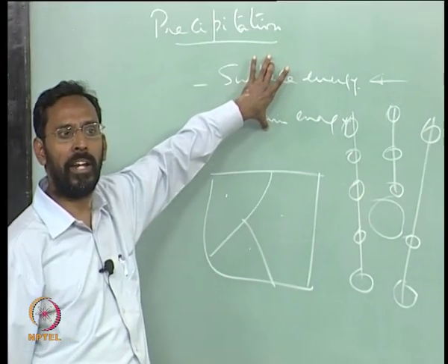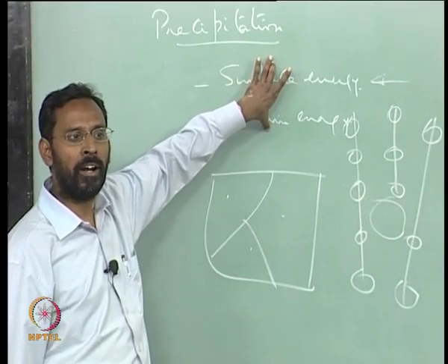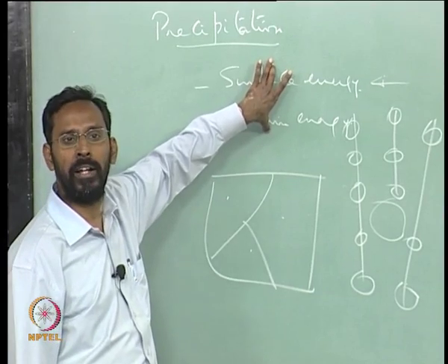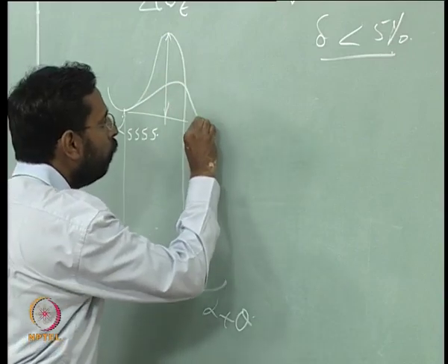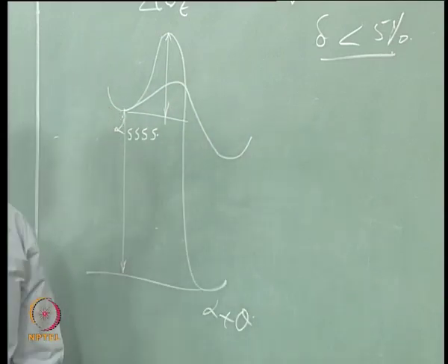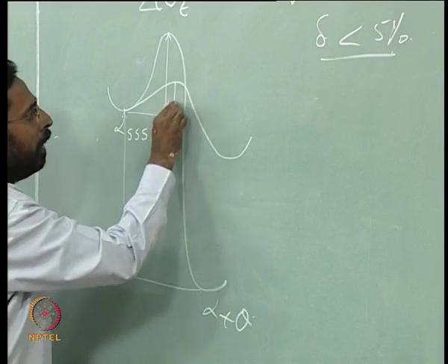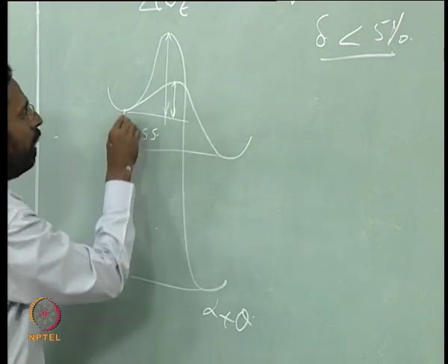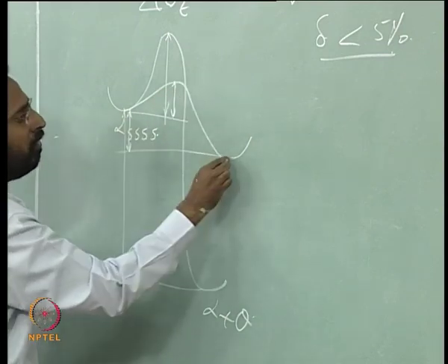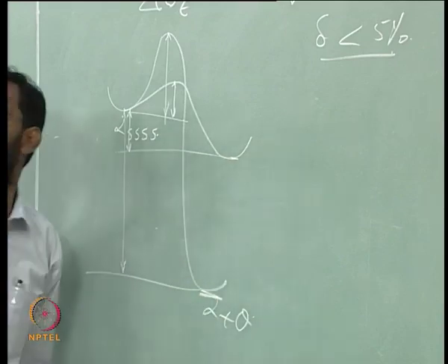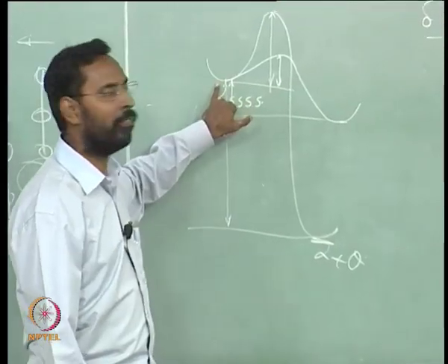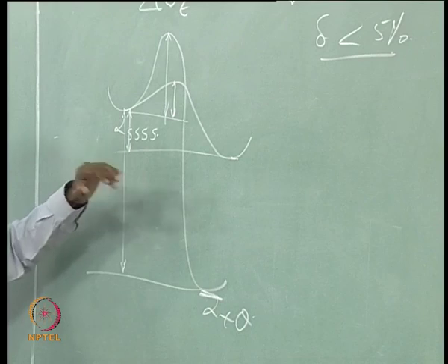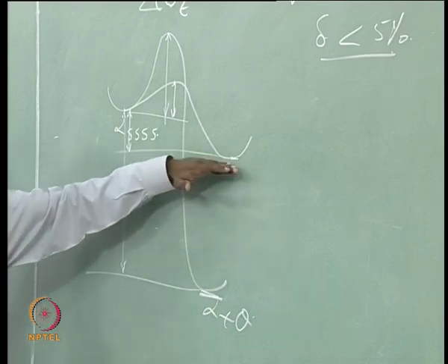What is the activation barrier? It is this, the combination of these two is the activation barrier, and the system tries to minimize that and gives you another precipitate with a lower activation barrier, but at the same time the energy of this will be higher than the energy of this, because that is after all a metastable phase. So a metastable phase comes out of this, and there is definitely a driving force for this to come, because this has a lower energy than this.